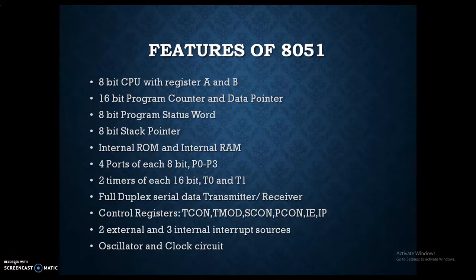So the features of 8051 are listed as this. You can see this 8-bit CPU with register A and B. That A register acts as an accumulator also, and there is a 16-bit program counter and the data pointer, and an 8-bit program status word, that is PSW, that is like the status register of 8085. Stack pointer is 8-bit.